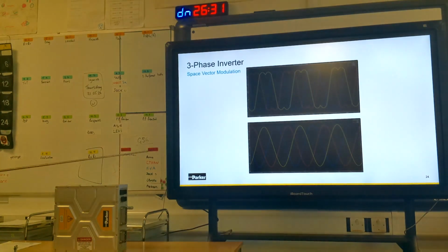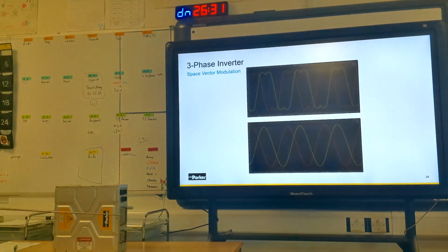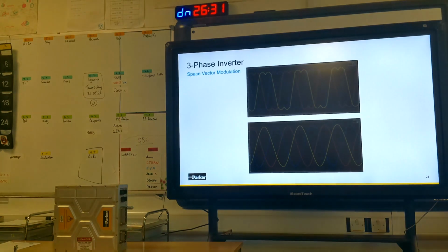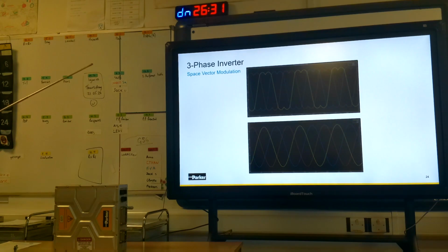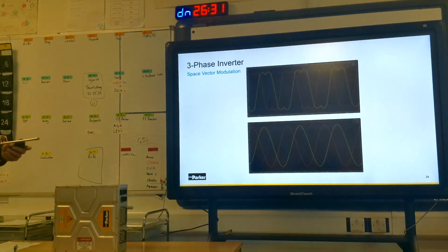Well, it turns out if you look at the harmonic spectrum of that, what you will find is it's got the fundamental, but then it's full of tripling harmonics. So, I'm going to get this right, a sine wave has half wave odd symmetry. If you look at any waveform that's got that property, you will find that there are no even harmonics, okay?